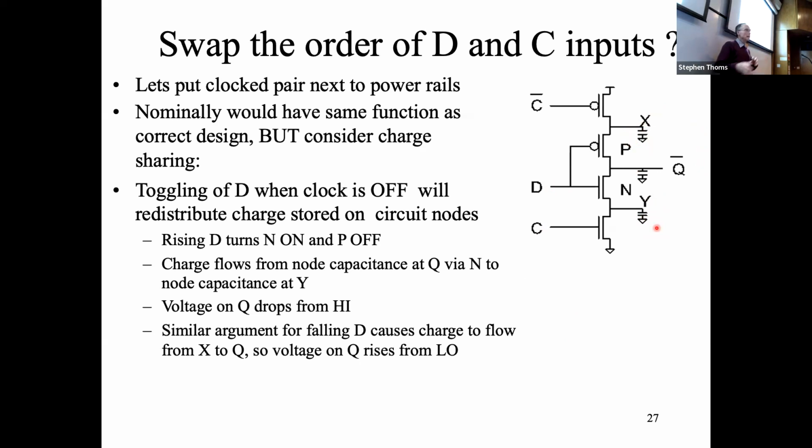And when the output is in the high impedance state, we're usually relying on stray capacitance or input gate capacitance to keep it in the state it was in before. Okay, so although it's a high impedance state, it's not just the fact it's high impedance that we're concerned about. We're also concerned whether it used to be a 1 or a 0, and we should stay at 1 or 0, at least for a period of time until the charge leaks from the capacitor.